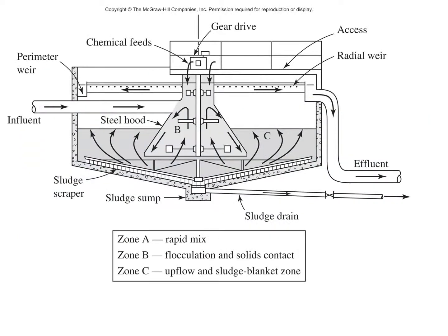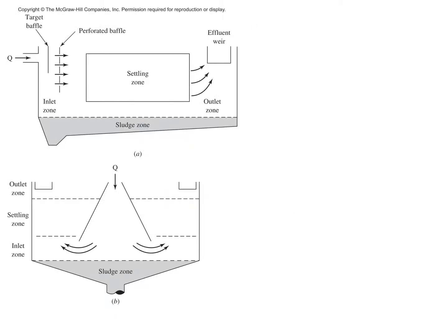This is one sample. Here you see another view of a settling tank. In the settling tank, you have influent, effluent, and a sludge blanket, and there is a bridge here. At the bottom, the bridge spins and collects all of the sludge that sinks to the bottom, and the effluent, which is the cleaned wastewater, you collect from the top. Again, this is another view. You see water enters at the left, and then you have the settling zone and the sludge zone at the bottom.